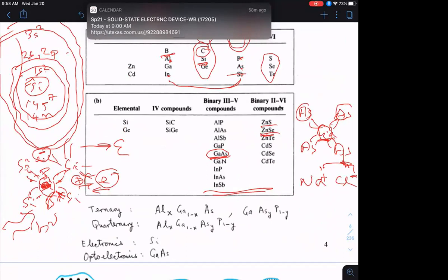As you go along, we'll see that because of these electronic properties, silicon is wonderful for electronic applications such as transistors, but unfortunately, it's not very effective in terms of absorbing or emitting photons. I'll get into the details in chapter 4. That's why many optoelectronic devices are made in things like gallium arsenide or other compounds.